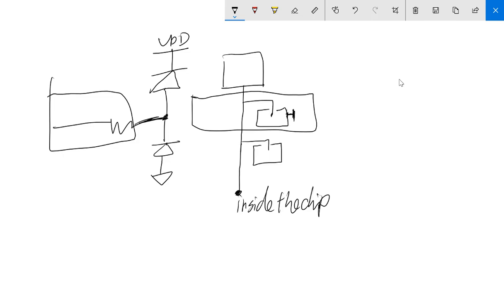So because this is metal one, and you connect to another one, and this one has a direct connect to metal three, and this is metal one, metal two connector, and that's metal two, and that's metal one. Okay, and this is metal three. So the yellow color, right, is metal three. So nothing is being shorted because metal three is on the very top layer.